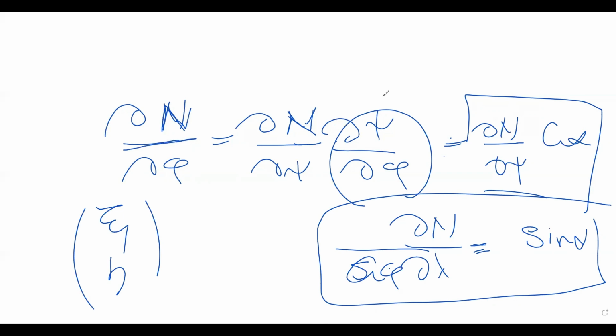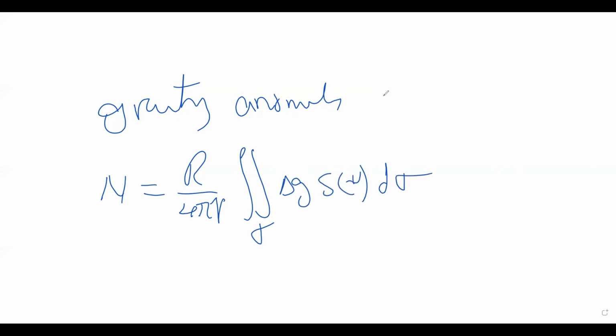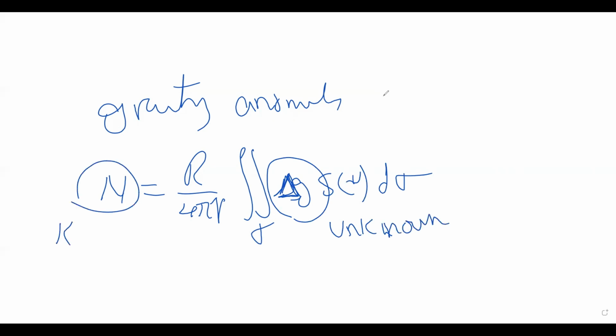So now the question is how to determine gravity anomaly, for example. If I have N, it means that I have SSH, and I have removed SST from it, then I have this integral, which is well known as the Stokes integral, as you know. Then I will solve this integral reversely. It means that I consider delta G as unknown and N as known.